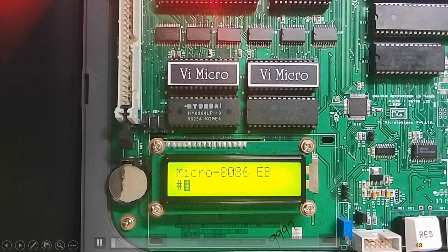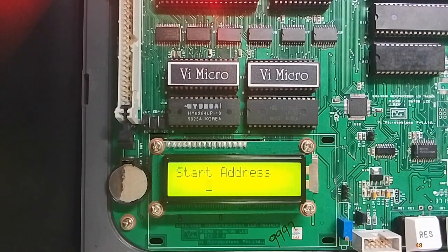Already I have typed the program, so I can start with command U itself. U, followed by the starting address of the program, which is 1000. Enter, enter. CH is equal to 04, which means move CH comma 04, CL comma 04. SI starting address, A which is going to be replaced, and after that BL SI plus 1.